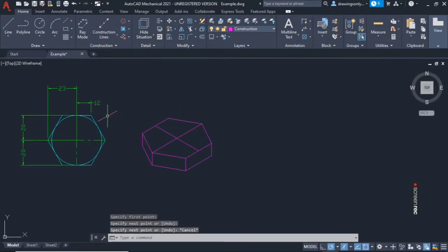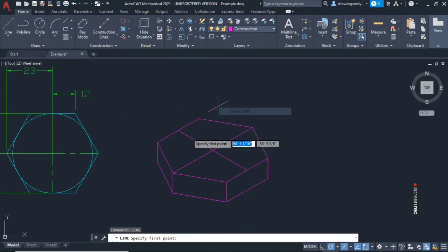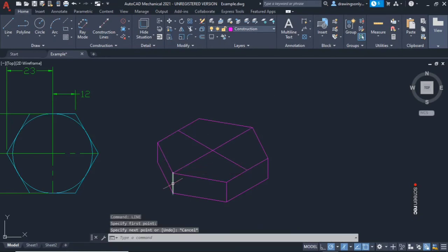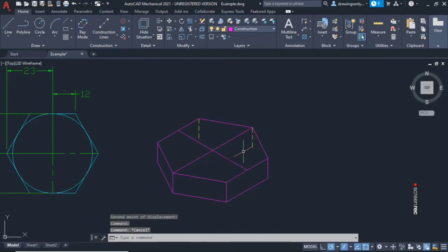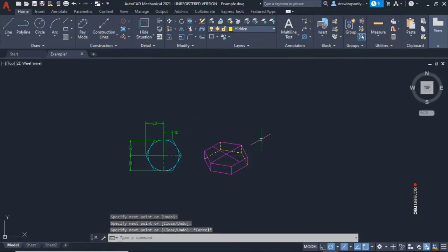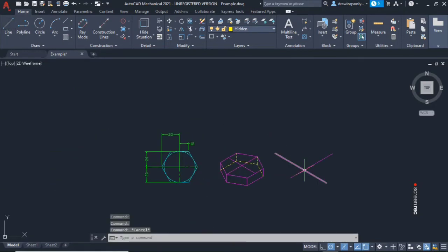And what I'm going to do, I will draw in the hidden portion of the nut that you can actually see from behind. So this is sped up a little, but I'm just copying in that line coming down, and I'm going to connect the base points so you can actually see the hidden detail of the nut.